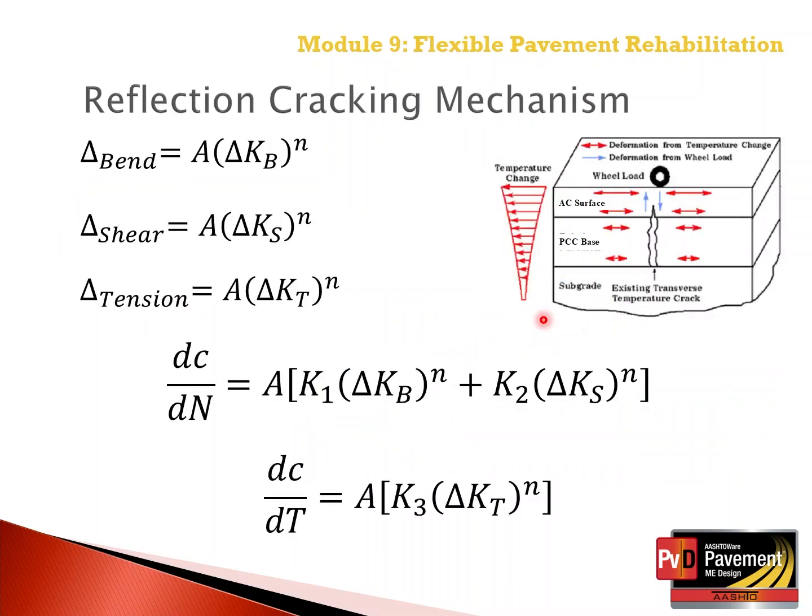This illustrates the reflection cracking mechanism in terms of the differential movement from bending, shear, and tension, which is related to the increase in stress intensity factors for each.